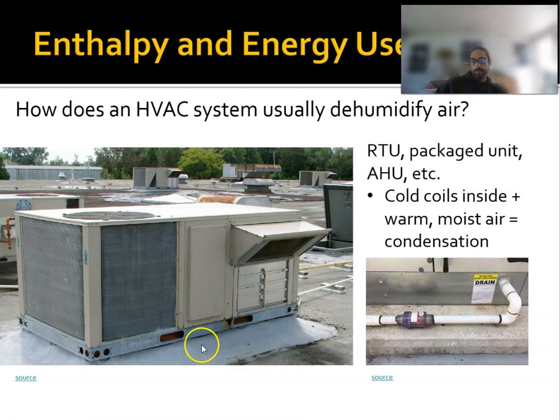So that's just the basics of it. We'll go over this in more detail later on. But the point is you have warm air that comes in here, condenses, dumps some of that heat out, comes over here, pulls heat from the air, and that makes the air cold, and then you blow the air down through the ductwork. In this evaporator step, you may cool the air down below the dew point, which then creates liquid water. And that's why you see condensate lines on all air conditioning units, right?